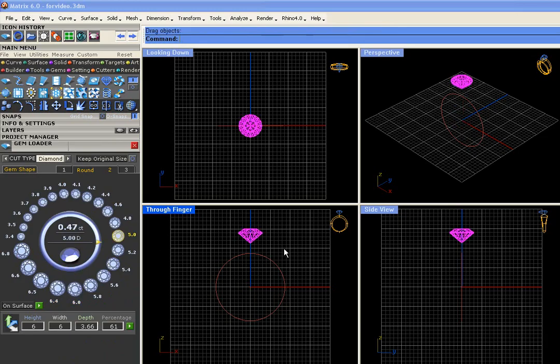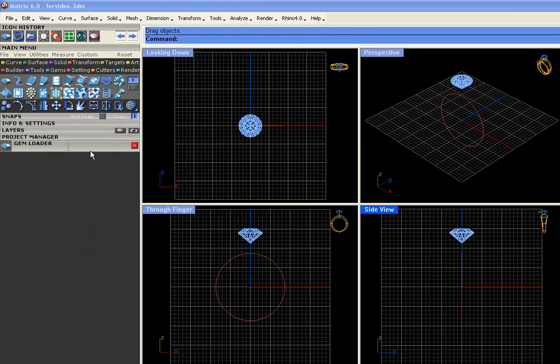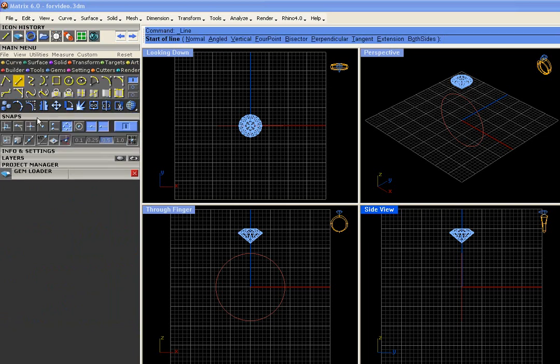Okay. This setup begins with curve from two views in order to get a sweeping crossover profile that goes this way, and that also completes the taper of the ring. So to take a look at that, we'll go first to the curve menu. And I like to use the single line tool to help me draw these little cues for the blend command.